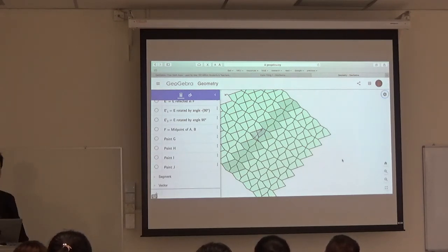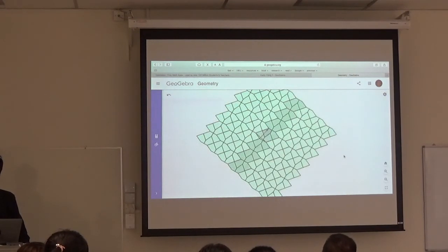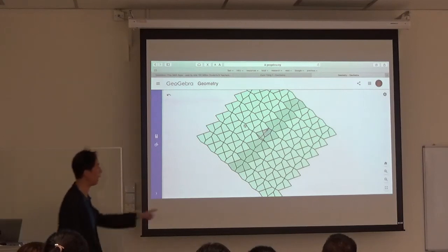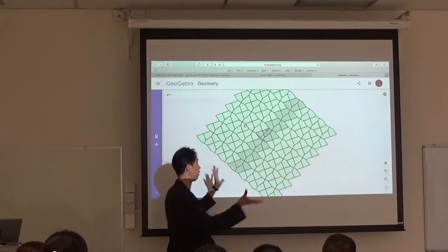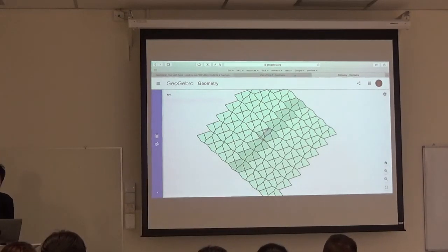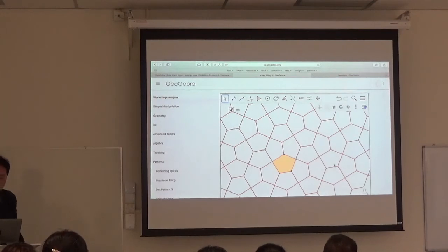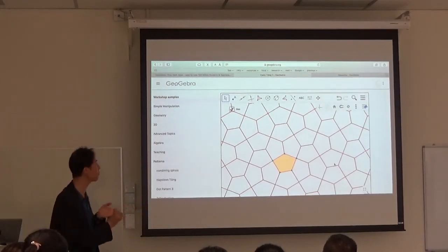You can make it just one entire combine then. But of course, you can practice later, right? Whether you want to shorten it or maybe combine it together. So that is one way to do the tessellation. If I open the point again, then you can continue to modify it. The whole pattern is still the same. So this is what I like to try to demonstrate, how we use the geometry tools for construction.